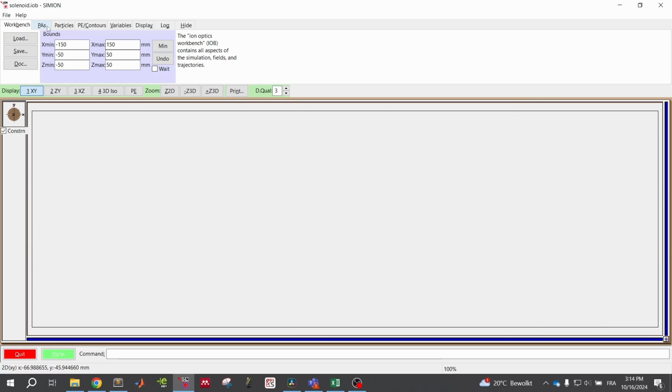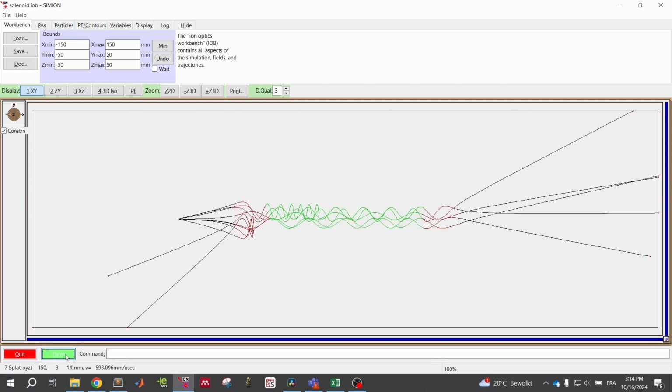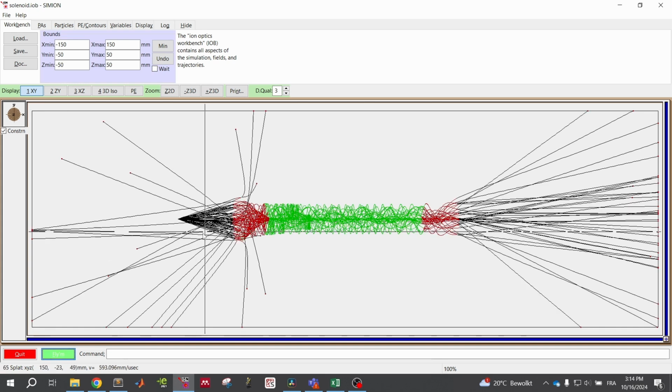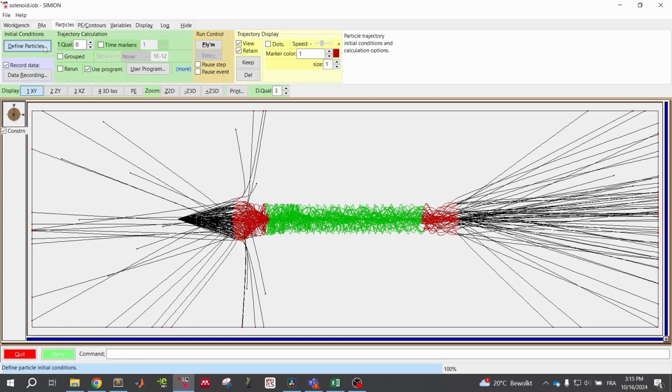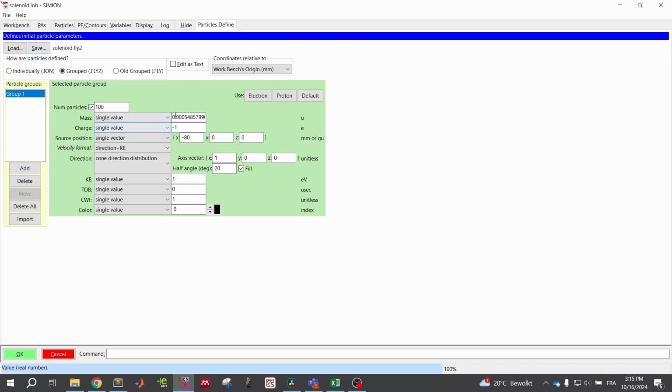With the integration function support of SIMION, you don't create a solid solenoid. It is just overriding the magnetic field in the PA instances, so you cannot materially visualize your solenoid, but the magnetic field will be simulated. In a way, that's really interesting because unlike electrostatic electrodes, magnetic poles do not have a totally uniform magnetic potential across the surface. The color adjusts a visual effect.